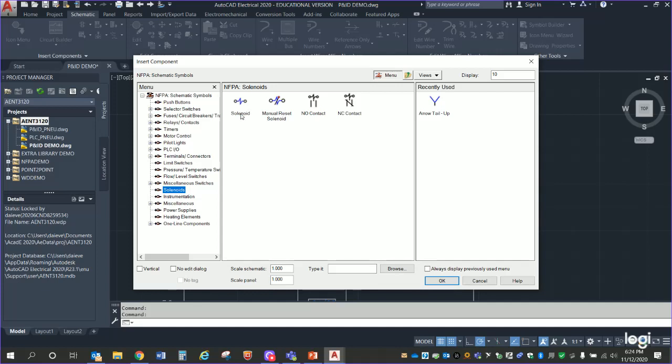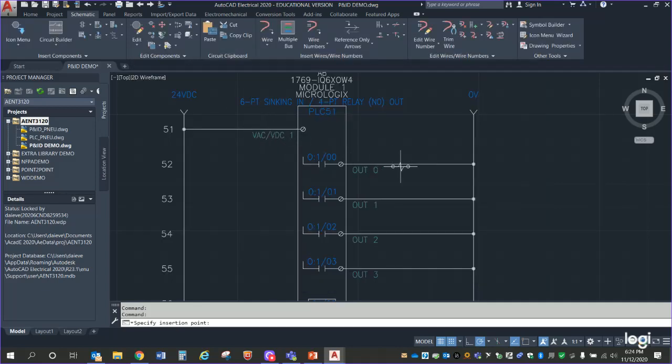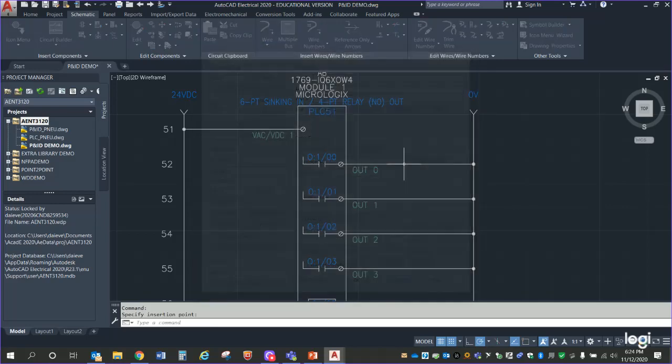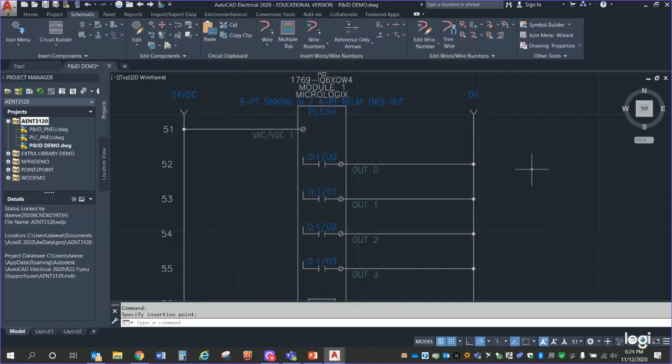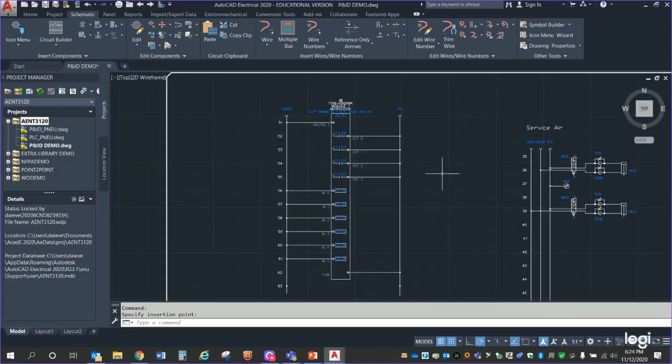Seems like a good place for it. So I'm going to go ahead and grab just the plain old solenoid. Now, what you're not doing this time is we're not talking about a relay with a contact. We're just talking about a solenoid. So I'm going to grab this solenoid. I'm going to place it right over here. Why am I not lining up? Did I turn off my snap? Oh, I think it might have been off when you moved the whole thing. Oh, no. So if you select it all and move again. Can I turn it on right now? Yeah, there we go. Snap is on.